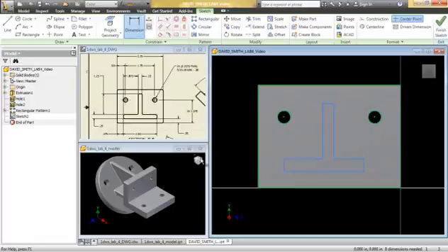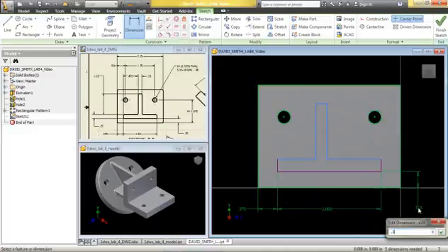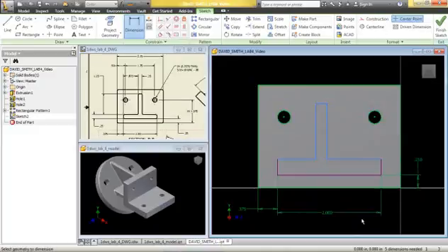So we'll go in with the dimension, and it says from the left edge to this left edge we need 0.375. The overall length from this line to this line looks like it needs to be 2 inches. The height from the bottom up to the bottom of the T, 0.25. The thickness of that T is 0.25.